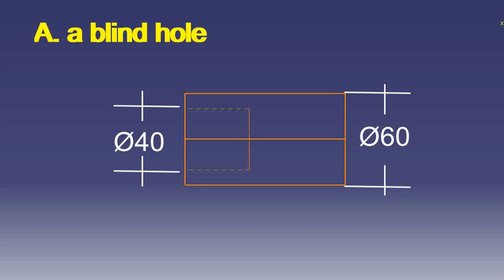We draw the hole down to its specific depth. At the bottom of the hole, we draw a horizontal hidden line that represents the flat bottom of the drilled hole. Then, we connect the sides of the hole down to this bottom with vertical hidden lines on each side. This creates a distinct, closed shape in the drawing that clearly shows the hole has a finite depth. We then combine this with a clear note, like 40 diameter and 40 deep. This visual, combined with the note, leaves zero room for misunderstanding. The machinist sees exactly how deep to go, and that the hole is not through.